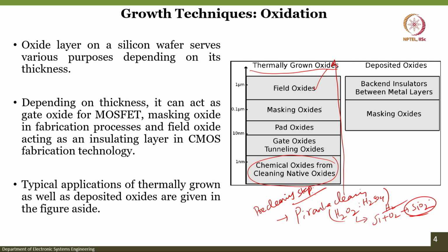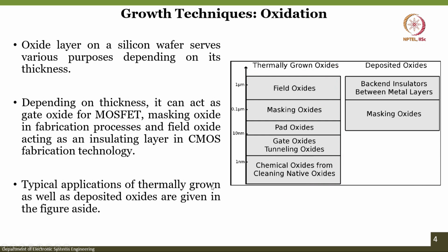Now, the silicon dioxide that is formed is in the order of a few nanometers, but the quality is not that great. So, if you do not want to grow silicon dioxide on top of this, once you complete the piranha, you can do an HF dip for 30 seconds, which is very dilute, a 1:50 ratio. You take water, 50 times, and then this is concentrated HF. After piranha, you dip the wafer in the HF solution, and you can remove the native oxide if one does not want to grow anything.